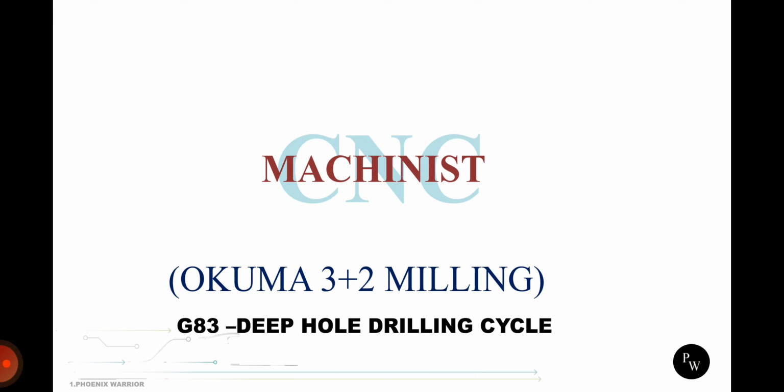In most companies, for efficiency purposes, they use the spot drilling cycle for soft material. In hard material, we definitely need to use the peck drilling cycle. In other words, they are adjusting some efficient parameters. The pecking depth is changed to around 5 mm, 4 mm, like that. So it will increase the overall equipment effectiveness in the process.